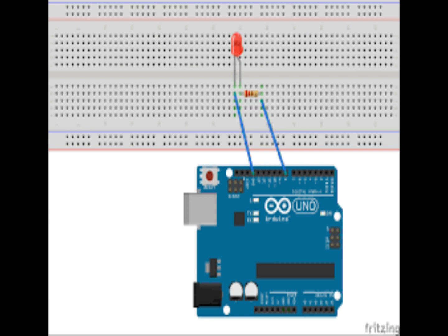Take an Arduino Uno and connect it to your computer using the USB cable. Next, take the simple LED. LED is the abbreviation of the light emitting diode. It is usually made of gallium arsenide or gallium phosphide, which are semiconductor materials. The LED has 2 electrodes, a positive electrode and a negative one. It lights up only when a forward current passes, and it can flash red, blue, green, yellow, etc. The color of the light depends on the material it is made from.